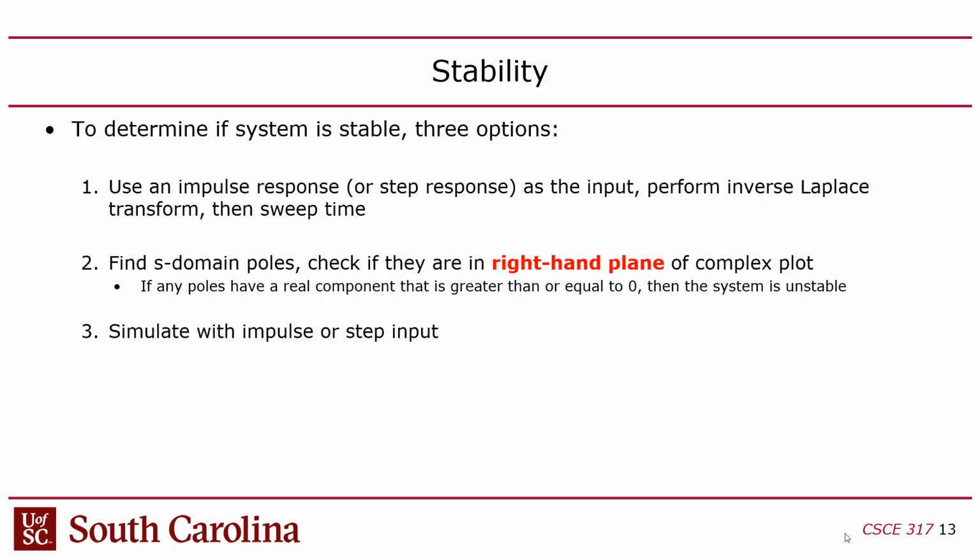So in other words, if you wanted to create a step function by adding together sine waves, you have to add together an infinite number of sine waves to get that step function. Although as you go to higher frequencies, the amplitude goes down. But it still has infinite bandwidth, that step function. And an impulse is kind of like a step function, except an impulse is even more generic, where it says, at time 0, I want to put infinity in.